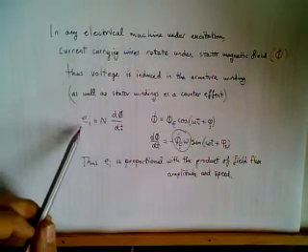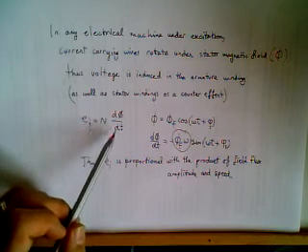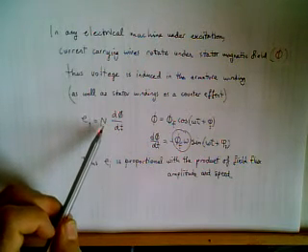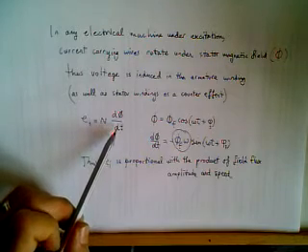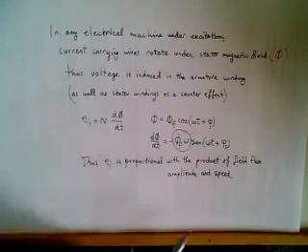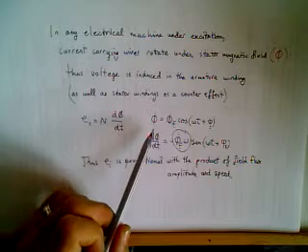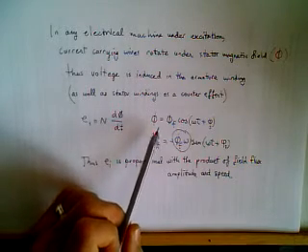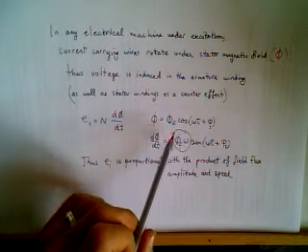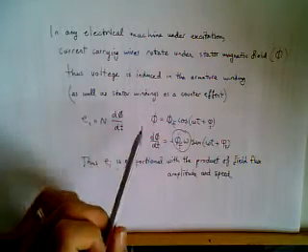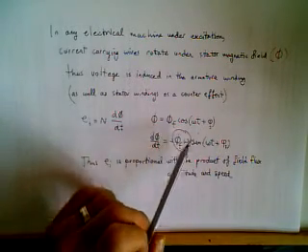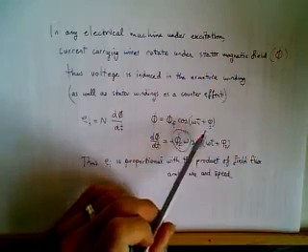So our formula is induced voltage is the flux linkage with respect to time, or the number of turns in the armature and the time variation of the flux or flux linkage. If that flux linkage can be expressed as a time equation with this form, its derivative will include some constant terms.